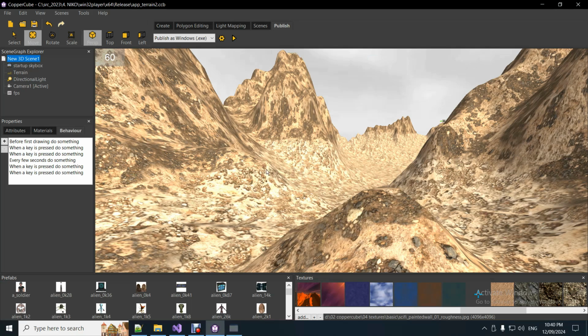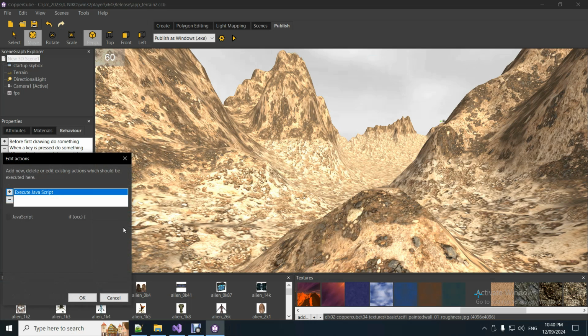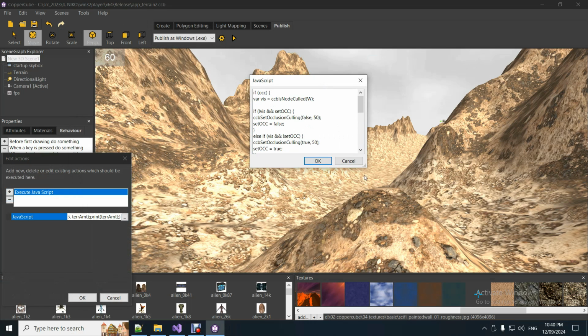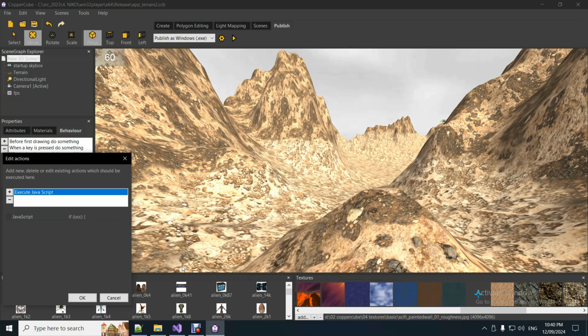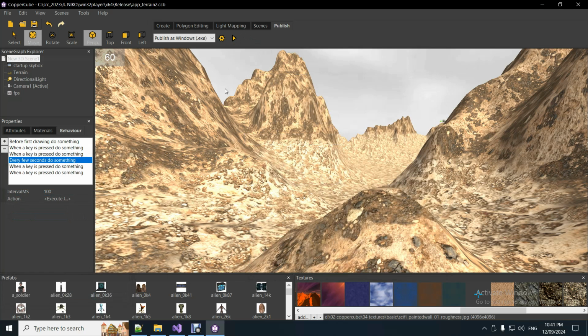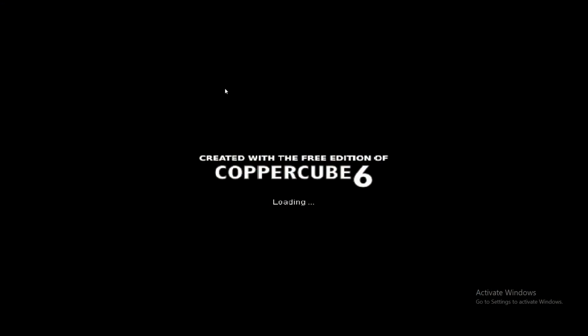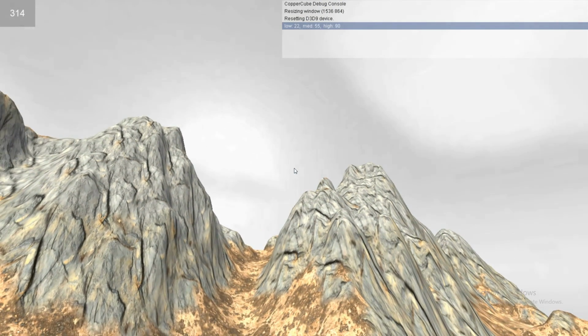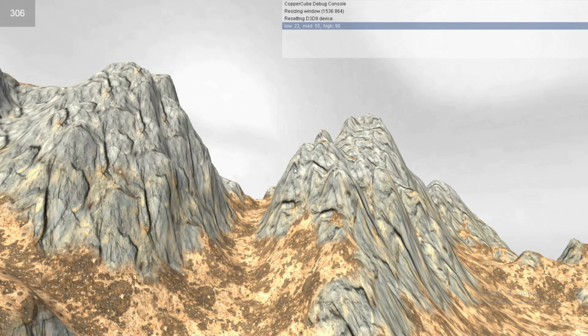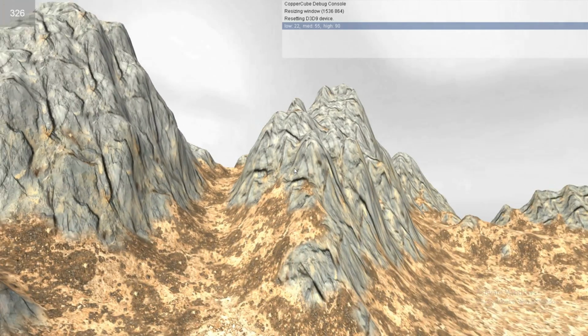I don't mind that. But if you were to put 1 instead of 0.5 here, I'll show you what I mean. It'll be a sharp cutoff then, and I think it'll look even worse if you ask me. So 341, 341. Run that. Update the angles. Update the top texture. It actually has to be a different texture than the one below it, otherwise you might find it updates the whole scene instead, so it won't work right.